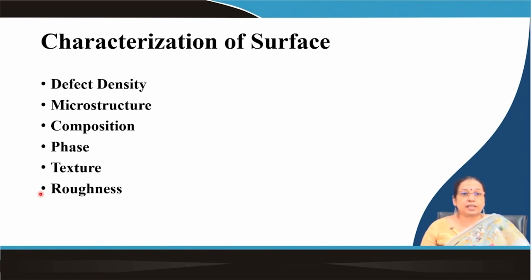So, certainly you will find that many defects, or you can say damage, initiate from the particular points where there is stress concentration, like fatigue crack initiation, pitting corrosion initiation, or stress corrosion cracking initiation. So, roughness also plays a very important role. If you think of the techniques applied for measurement of roughness, they are different profilometers, maybe laser profilometer, then optical profilometer, atomic force microscopy, and also scanning tunneling microscopy.